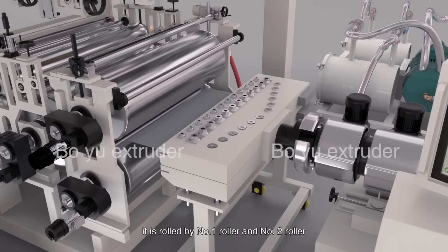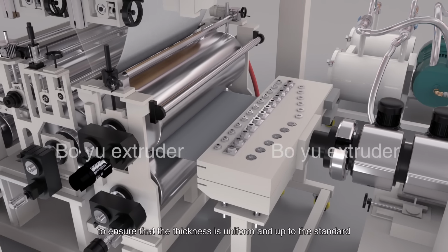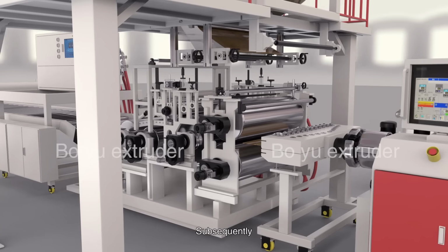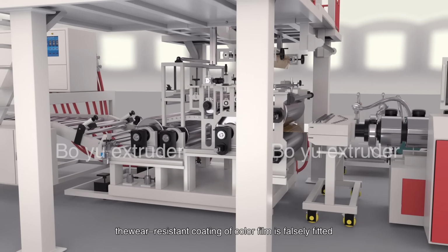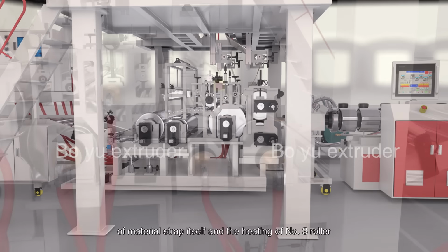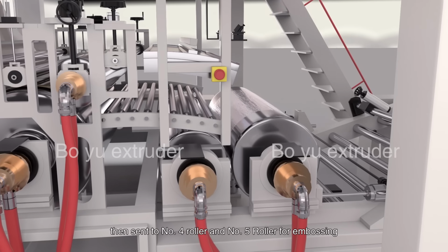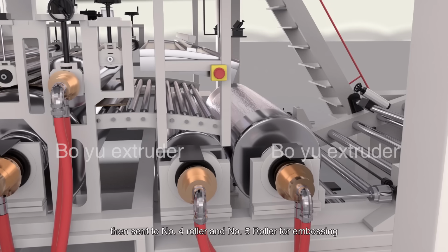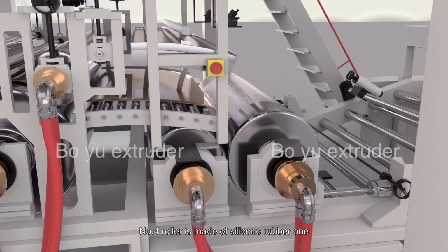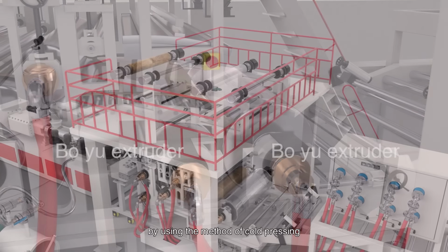Firstly, it is rolled by number 1 roller and number 2 roller to ensure that the thickness is uniform and up to the standard. Subsequently, the wear-resistant coating and color film are laminated by the temperature of the material strip itself and the heating of number 3 roller. Then it is sent to number 4 roller and number 5 roller for embossing. Number 4 roller is made of silicone rubber, which makes the embossing texture clear by the method of cold pressing.